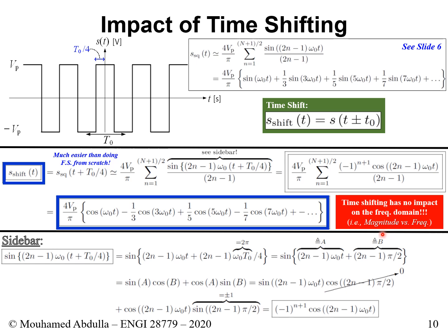And what magnitude is essentially, so if I ask you, what is the magnitude, what is the V peak of this thing here, the 7th harmonic for this one here? Some students will tell me, well, it's minus 1/7 volts. Well, the answer is wrong. We said magnitude, so you cannot have a minus. Also, it's wrong because you forgot to multiply by this. So the actual answer to the magnitude of this harmonic is 4 VP over 7 pi. And there is no minus because we take the absolute value. We're looking at the magnitude. So that's your V peak for this one.